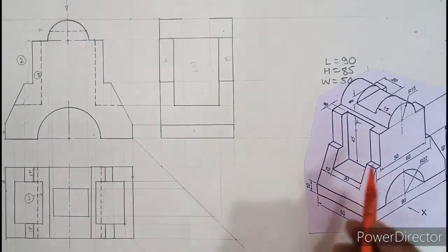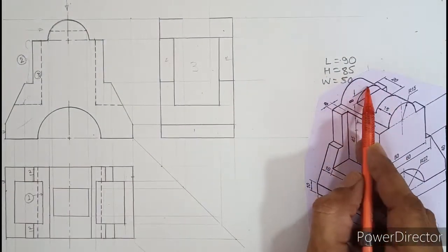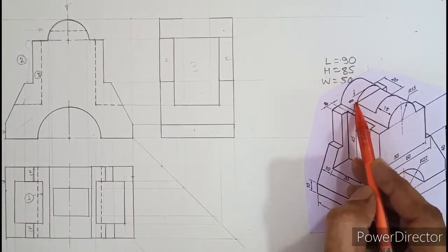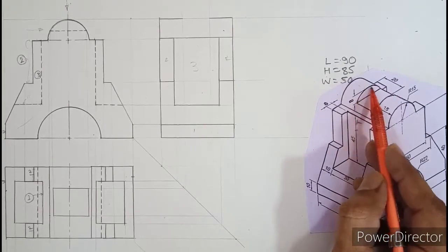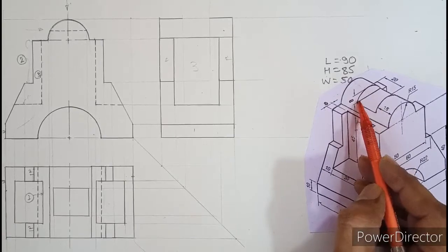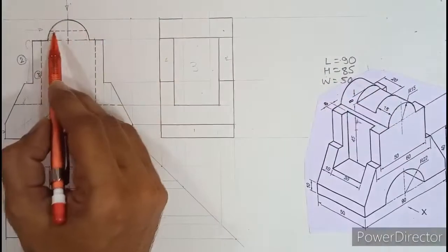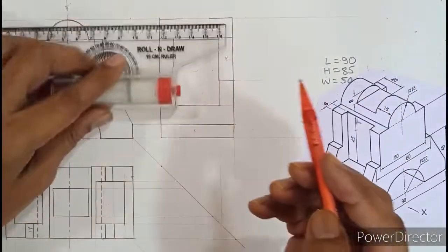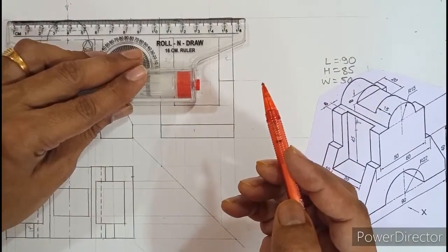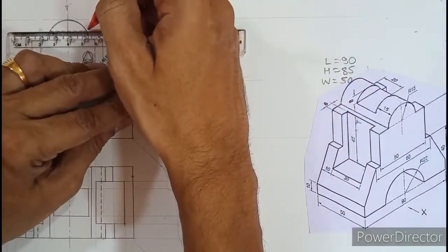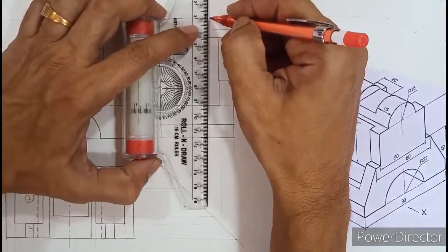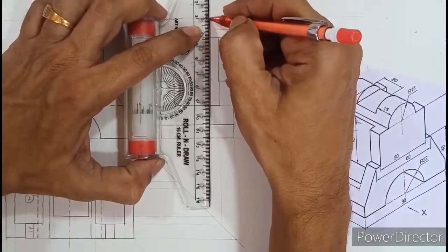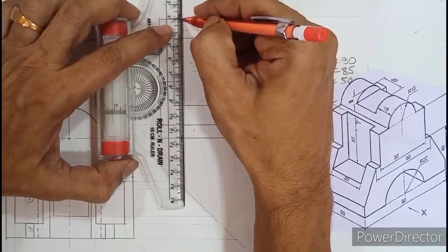Once this 15 mm is drawn, you can see this circular edge as a straight line which is coming 8 mm down. Have we drawn this 8 mm somewhere in the front? Yes, it was the hidden line. So this hidden line was 8 mm. From here, if I extend or project this 8 mm, I can get these 3 lines darkened, which will give me the complete cylinder.